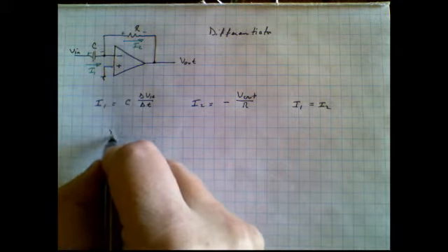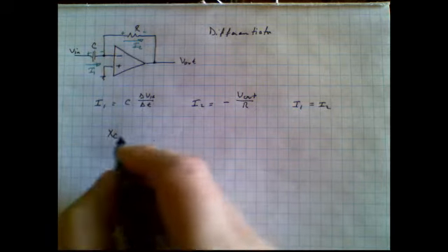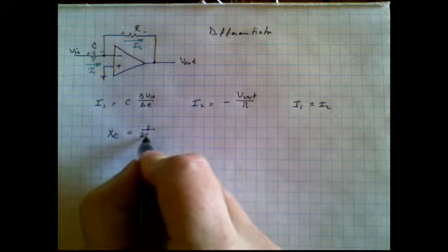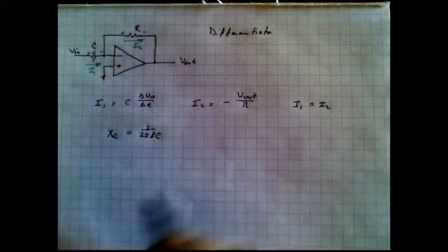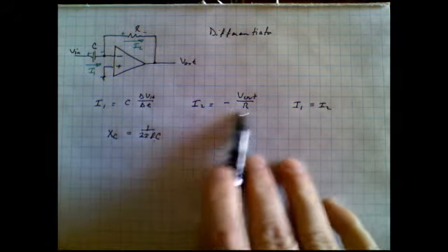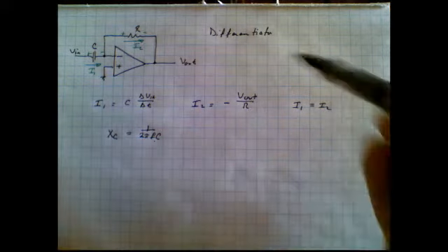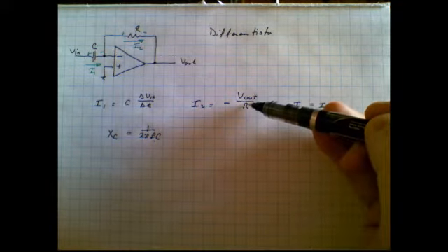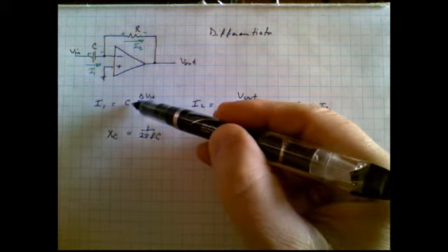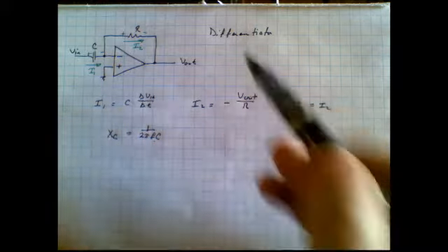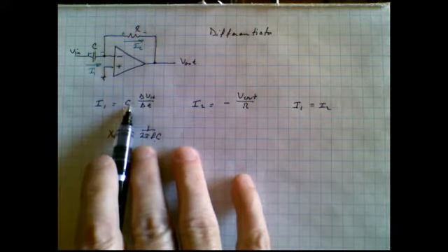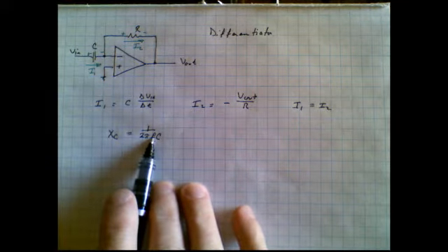Well, we'll just recall for a moment that the reactance, or the equivalent of the impedance of a capacitor, is equal to 1 over 2 pi f C, where C is its capacitance. So putting this reactance into an expression like Ohm's law, you can see right off the bat, hopefully, that if I have a fraction in the denominator, the C pops right back up into the numerator. So that's why the resistance is in the denominator here, but the capacitance is in the numerator. It's because the reactance is 1 over C.